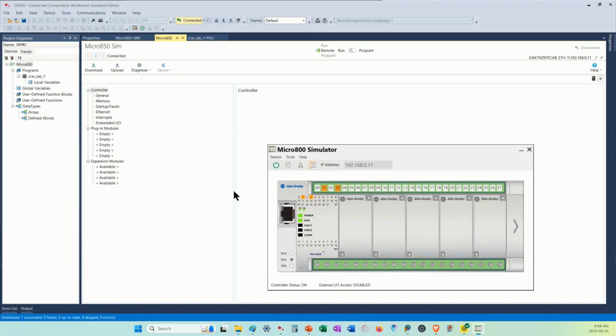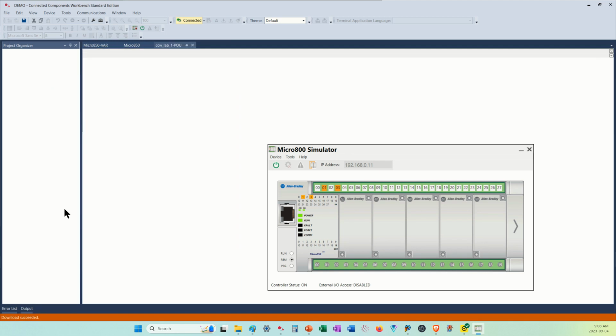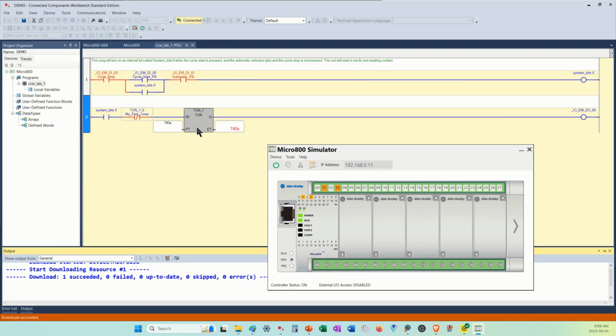And I'm going to go here so I can see that. There's my logic, nothing's happening. Notice that my TON_1 Q, the reverse contact, is in red because the timer is not energized, and it says I'm true if there's no energy. So I'm turned off. Okay, so what I'm going to do is hit this, toggle that, boom. Close that. Now my timer is not done yet, and this is going to flash so quick you won't even notice it. So this output should come on.